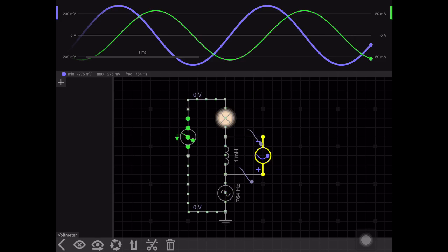So here the voltage across the inductor is what I am talking about. In an RL network phasor diagram, once again you see a phase which is less than 90 degrees. Here for graphical purposes I am showing you the voltage across the inductor as well as the current through the inductor. That will have 90 degrees itself. But when you take the resultant voltage and the current, then it will not be 90 degrees, it will be less than 90 degrees.